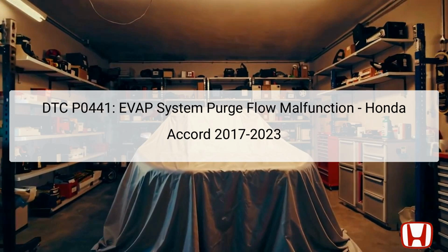The Evaporative EVAP system is designed to prevent fuel vapors from escaping into the atmosphere, thus playing a crucial role in both emissions control and engine efficiency. The EVAP canister purge valve is a key component in this system, located along the purge line that connects the charcoal canister to the intake manifold. Diagnosing this issue is critical, as it may lead to increased emissions and potentially affect vehicle performance.